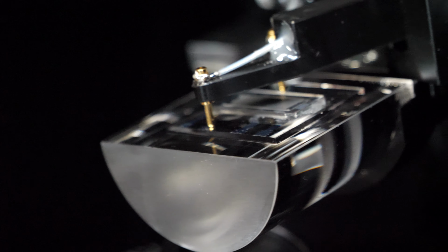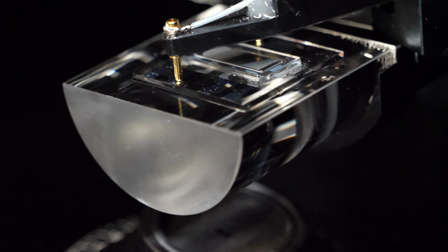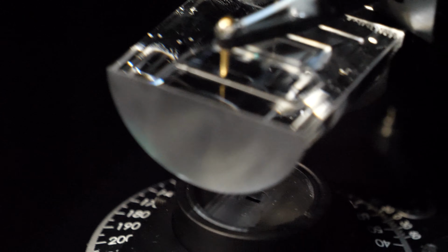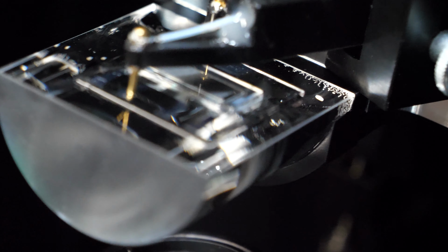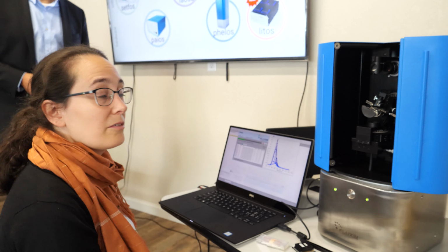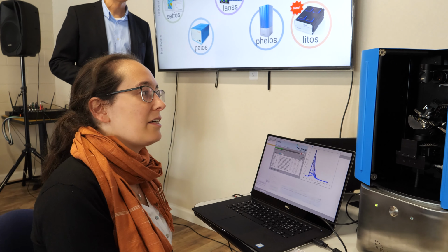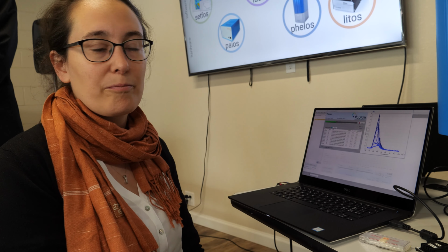From a former collaboration. So it's just a little sample of something there. It's not connected or powered on or anything, right? Powered. These two probe tips are connecting cathode and anode. So you're actually powering up the OLED. Yes. There is now 0.2 milliamps flowing through the OLED. So the whole point is you want to see it in action and see what happens. Exactly. We want to see the angular dependence of the OLED emission.